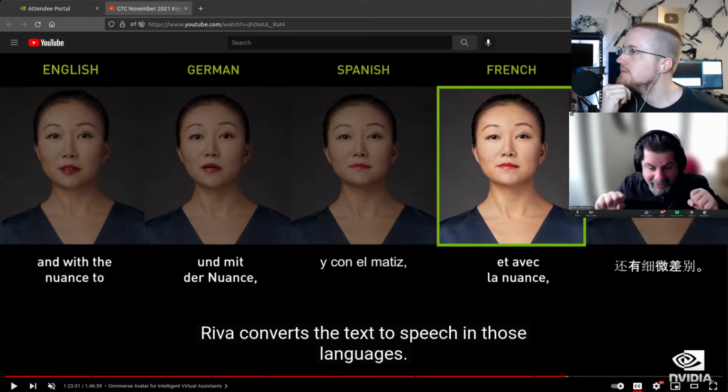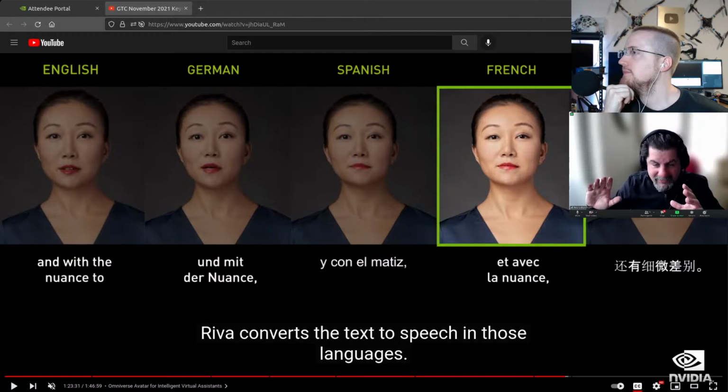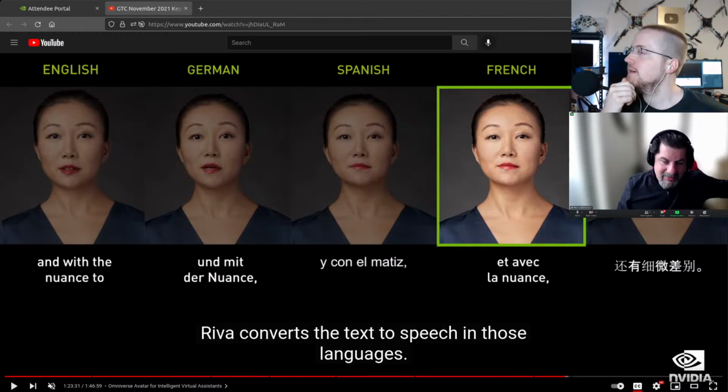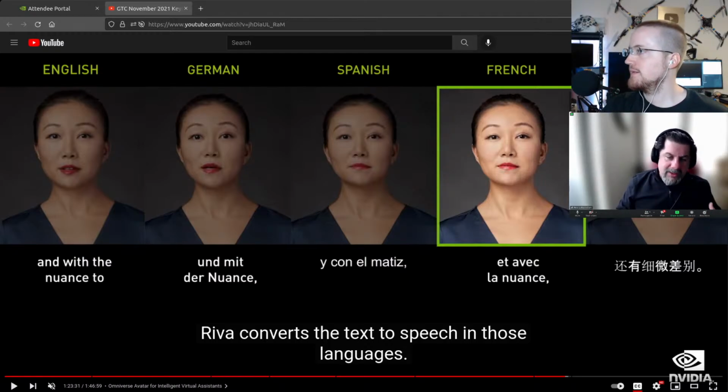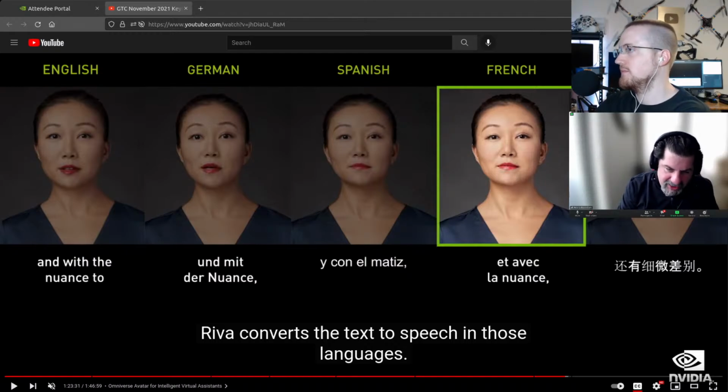And you can put on that headset and use that separate computer for VR, while the first computer can be used for editing or running the simulation in Isaac Sim. The problem you have in running it all on one computer is that you become limited to the total compute capabilities of that one machine.